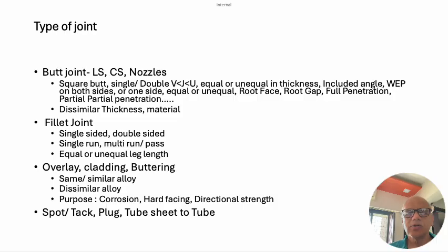So we must list out, for our job or for our type of product, the normally preferred or normally used joints in our manufacturing areas, and classify them to the extent possible. Make a table and recommend for different materials, for different processes, for different thicknesses, for different positions, all the variables a welder is going to be concerned about, and also depending upon the filler metal, parent metal, and the resultant chemistry.